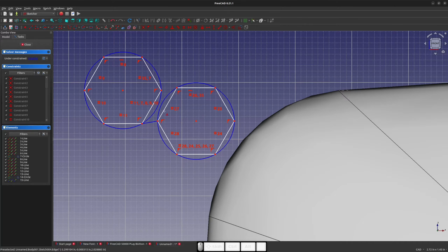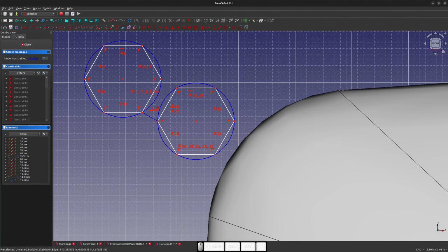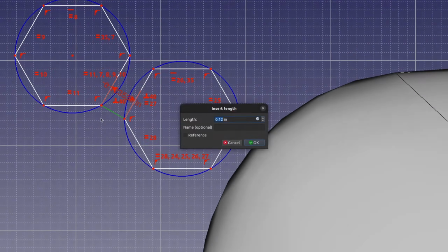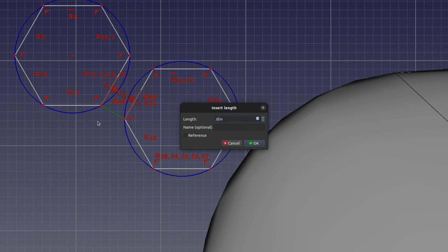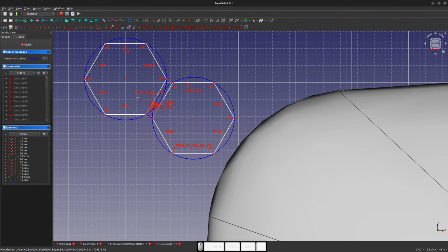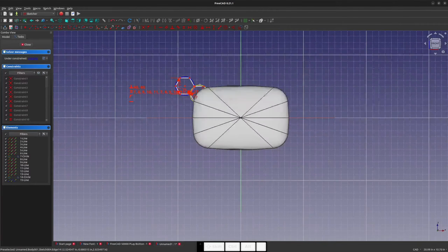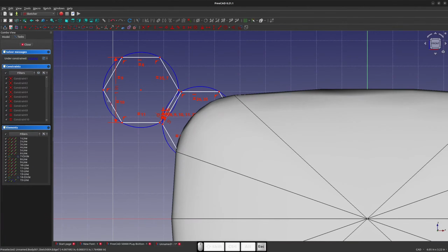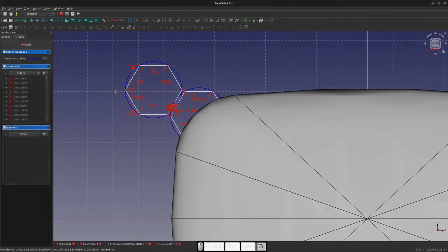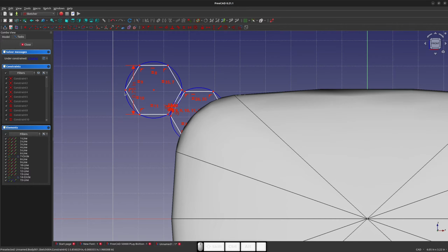We're going to choose perpendicular and make this line perpendicular. Then we can give it some hard dimensions. I've got this sort of diagonal dimension, right? Maybe I'll make that 0.05. And then I'll choose a vertical dimension, and we'll go from this point to this point. And I think 1 might be a good size pattern. Maybe I'll go 0.75. Yeah, that'd be cool.